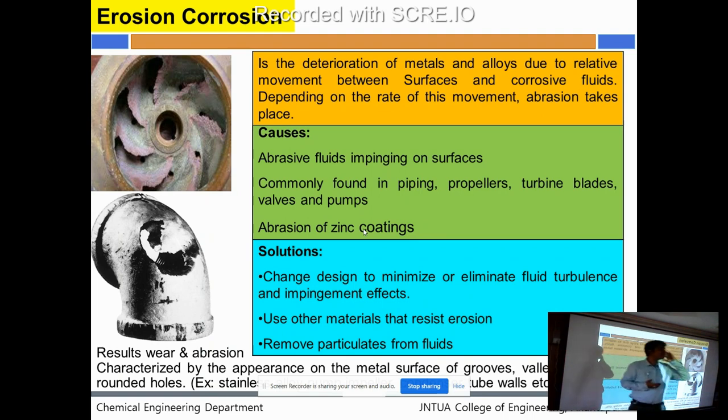We will think in a broader sense: if I increase the velocities, if I increase the agitation speeds, my production yield may be more. But you are looking at the production yield, and you have to think of the other consequences. As I said, with more agitation, what will happen? What is the polarization we talked about? Concentration polarization. More agitation means more pushing of H plus ions to the surface, and H plus ions will pick up electrons from the surface. So more corrosion.